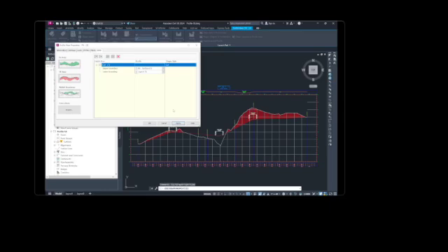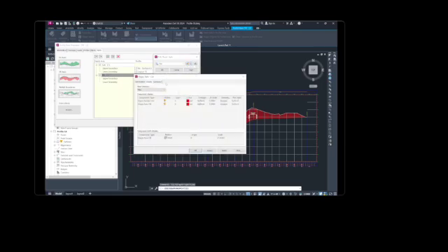Now we're going to define a fill area hatch. In the profile view properties box, on the hatch tab, click the fill area. And then a fill one area is displayed in the hatch area table. For the shape style, click the standard entry, and then in the arrow down, we need to go to edit current selection.